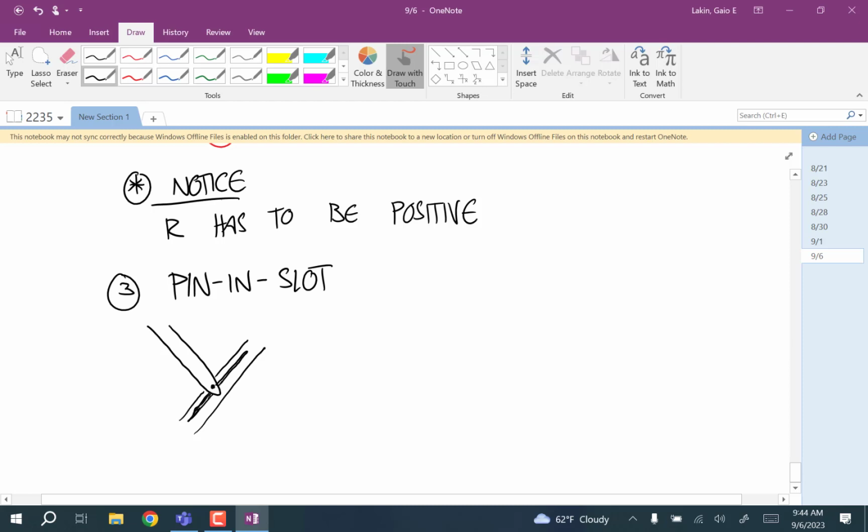I can show you exactly one of these. I have it sitting right here. It's sort of small, so it's hard to see. But if you think of the one I'm holding here as body 2, and this one up here as body 1, you can see this thing is free to slide along this one chosen axis. But if you try to pop it out of there perpendicular to it, it can't move perpendicular, and it's free to rotate, okay? So there's one single force that resists translation perpendicular to the slot. Everything else is free to happen.